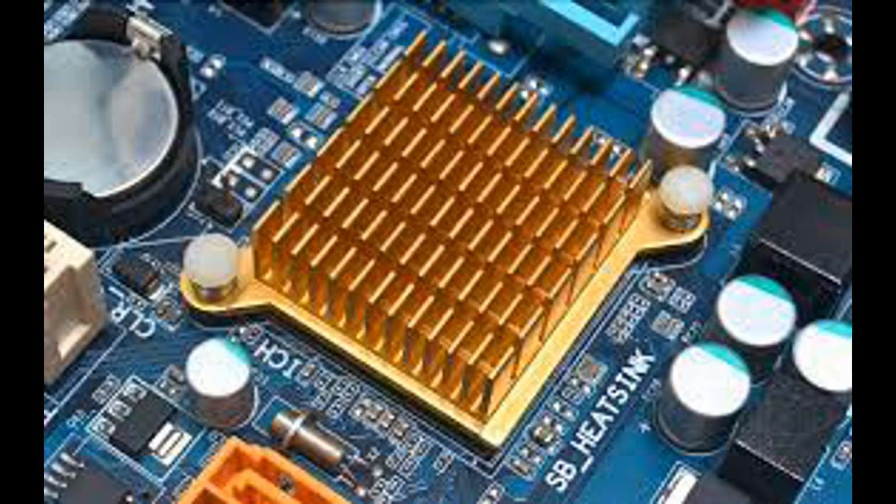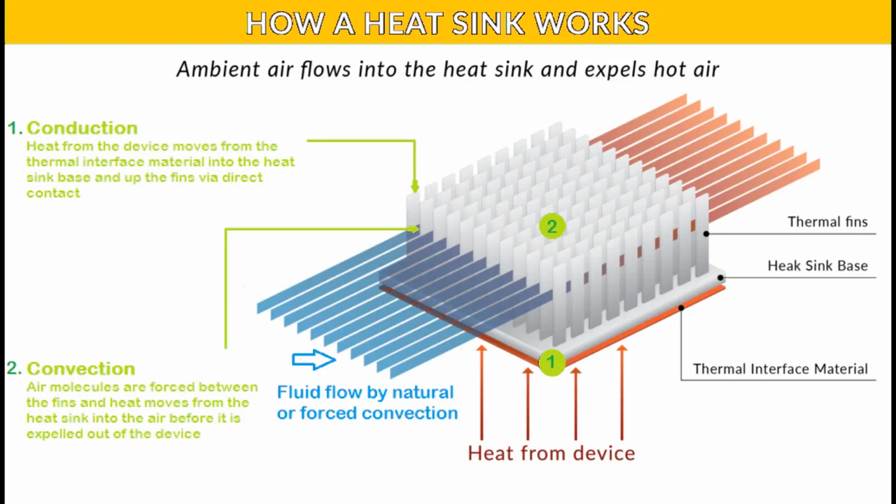Thermoelectric heat sinks offer several advantages and applications. Precise temperature control: thermoelectric heat sinks can achieve precise temperature control by adjusting the magnitude and direction of the electric current flowing through the thermoelectric modules. Compact design: thermoelectric heat sinks are compact and lightweight compared to traditional cooling solutions, making them suitable for applications where space is limited.